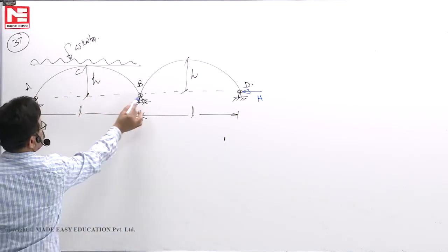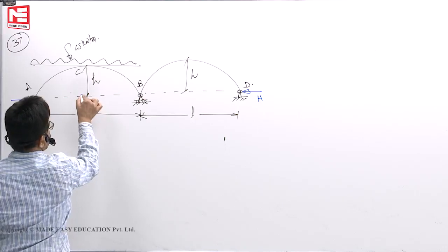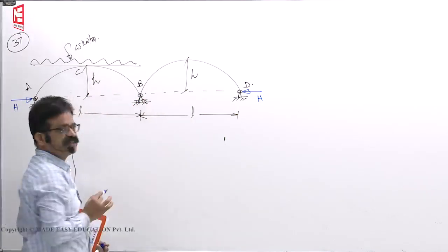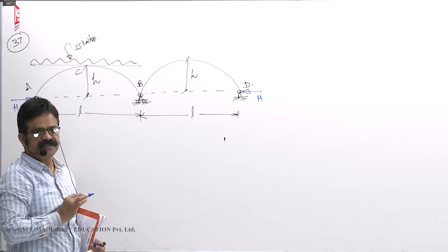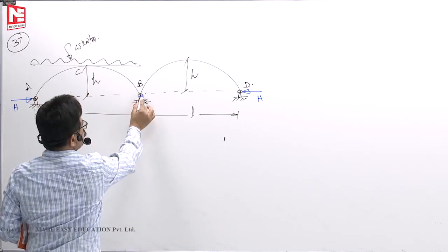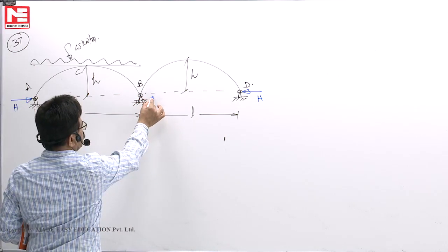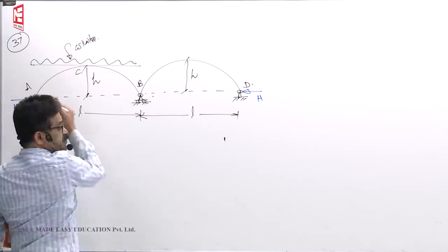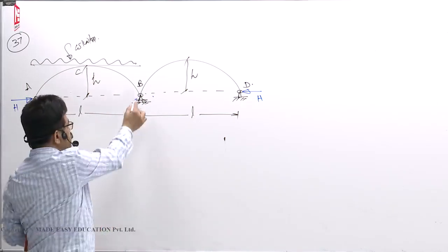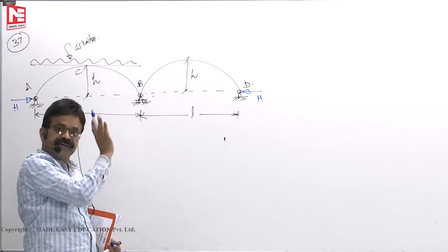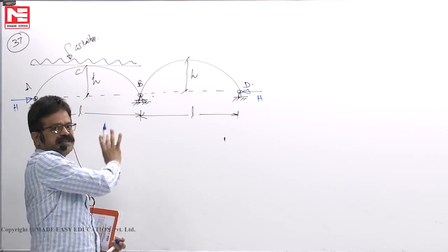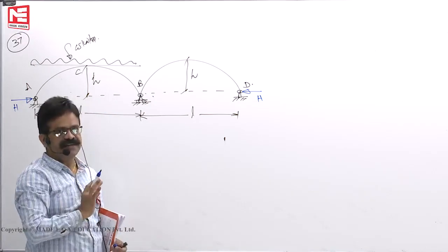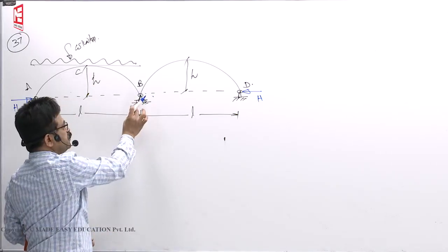Now this roller, because when you are pressing it down, will sway towards the right by some amount delta. So this moves to the right side. For such a case, H will not be wL square by 8h, because it should remain there only. If it remains there only, the wL square by 8h formula is valid for this span.